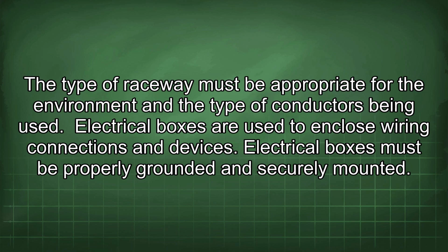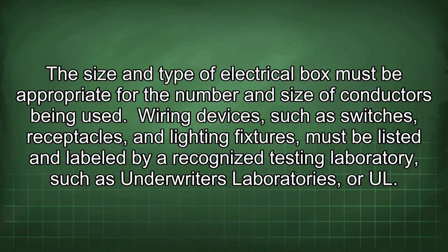Electrical boxes are used to enclose wiring connections and devices. Electrical boxes must be properly grounded and securely mounted. The size and type of electrical box must be appropriate for the number and size of conductors being used.